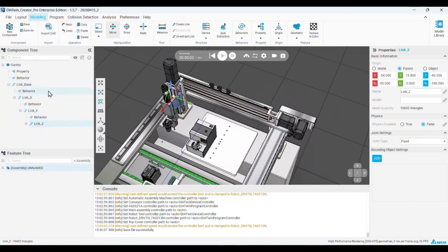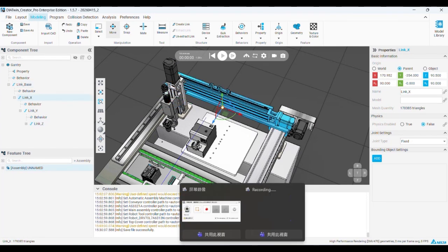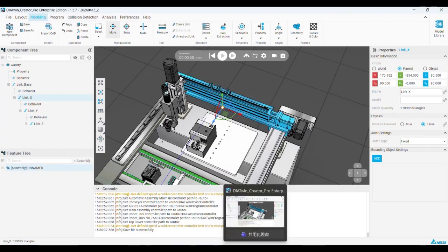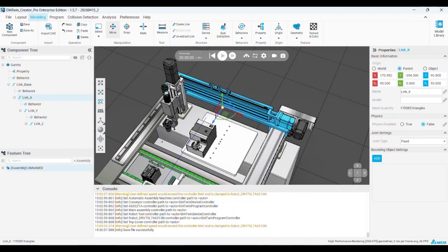Okay, so the first thing, you just use extract link to define what is the moving part and what is the stationary part. Okay, this concept is just the same as the air cylinder. But this one is the XYZ table. So maybe on the X there will be Y, on the Y there will be Z, right? And on the base there will be XYZ. Okay, you have to be like this for this kind of structure. Typically we need to also set the range and the direction of each link.